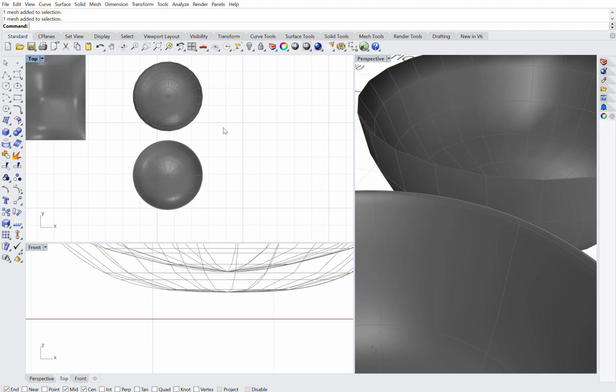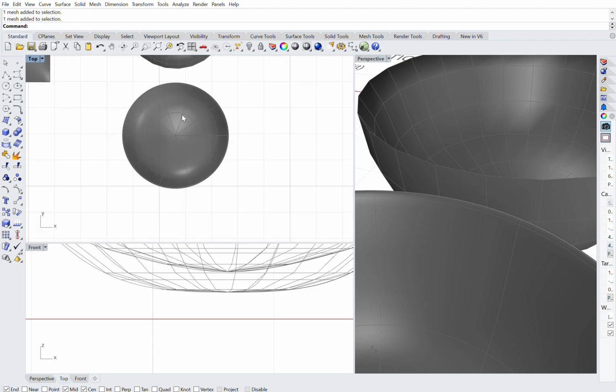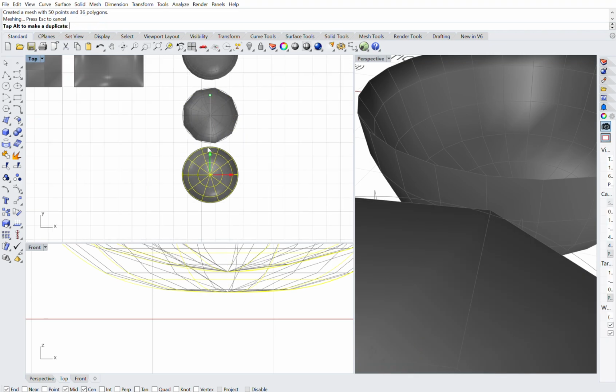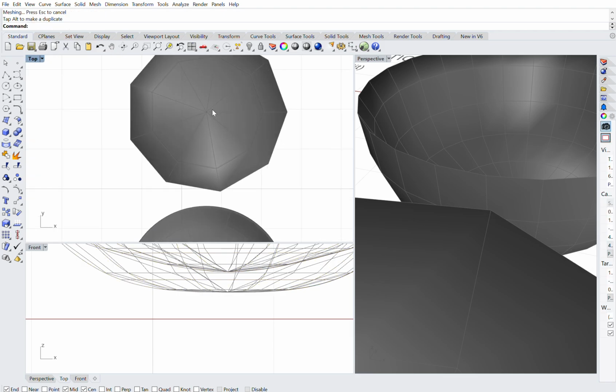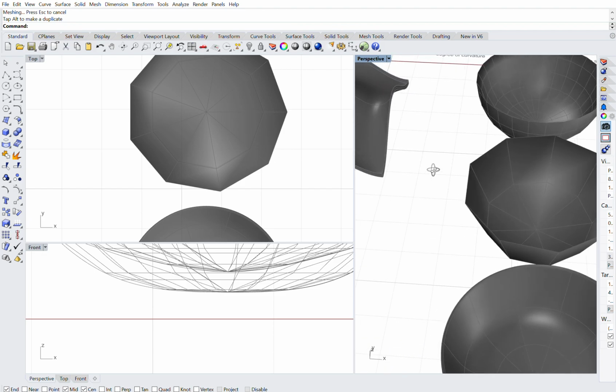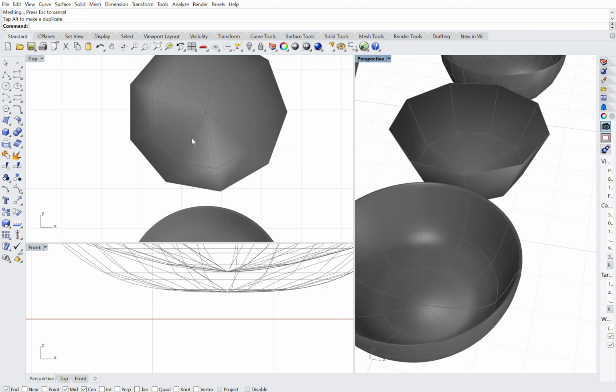So I think for this exercise, let's just demonstrate using a lower polygon count on the mesh. So let's do that again. Mesh. Okay, so to make it less, I would just increase this to say 13 and 13 edge length. All right, so now we have something like this, that's close to, but similar to the scale and the look of the original bowl.